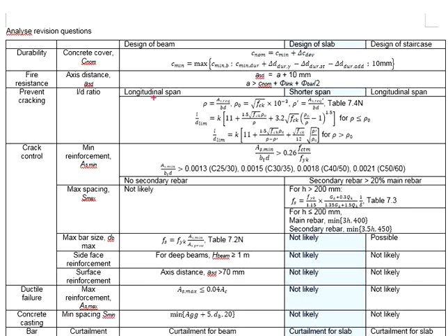You can see in the summary table here all the structural elements, beam, slab and the staircase, would require the checking for the L per D ratio. Even though they are all required, their applications vary slightly. You are checking the deflections along the longitudinal spans of the beam, this one without any argument.